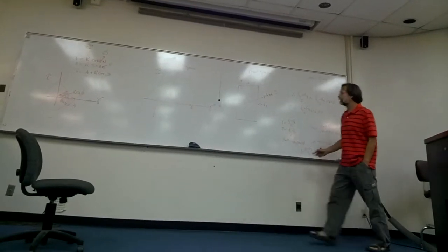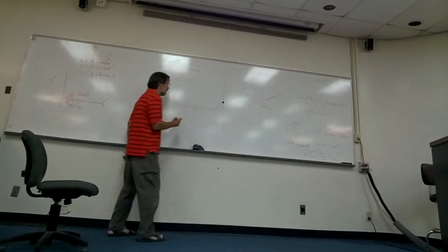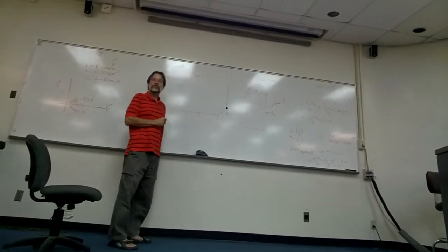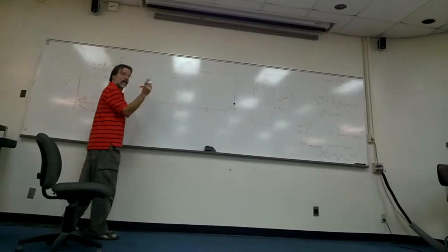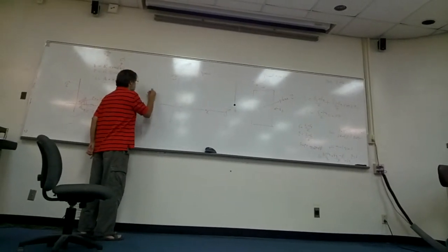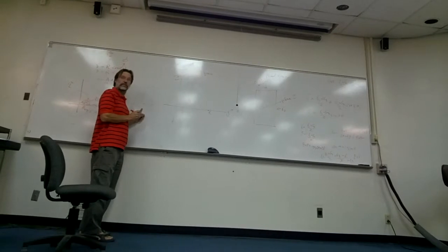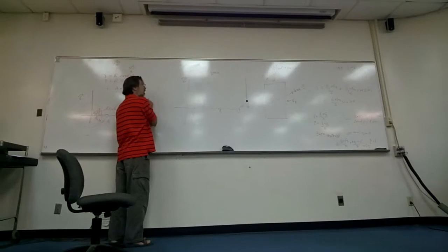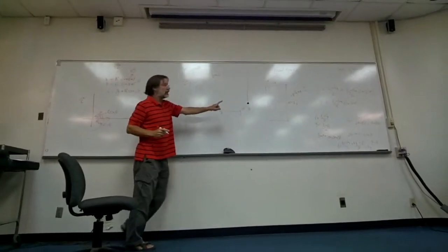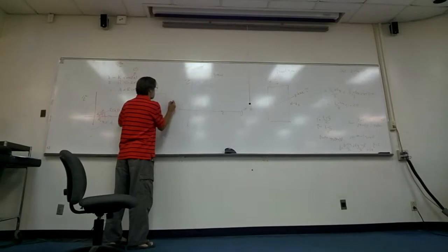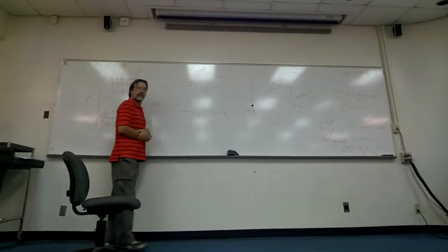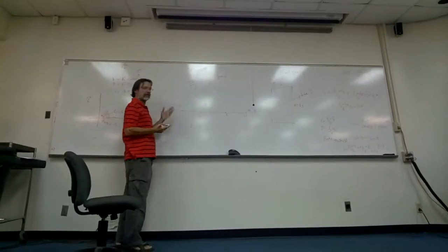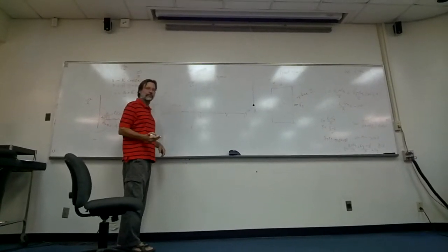That one I can plot. This is why I'm doing it this way. The other quantity will plot on this axis. Let's turn that around for a second. What does that represent back in real space? Here's the critical issue: the minimum and the maximum stress. This is sigma 3. Remember the angle theta. When theta is 0, that's that plane. Perpendicular to that is sigma 1. Well, it better be there because that's the way we define it.